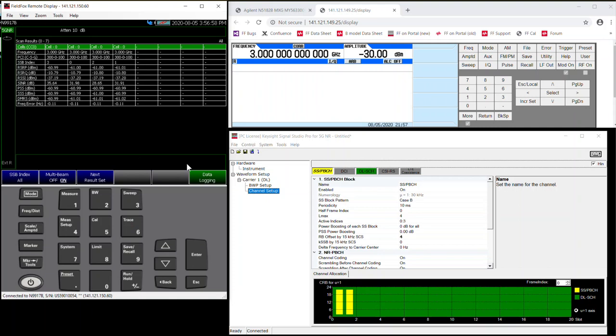Okay. The first thing I wanted to go through is some power level changes because this is an RSRP of minus 61. You had a little bit lower power, so we'll go ahead and drop the power down. Let's do an increment set of 5 dB. And I'll just keep lowering this, and you can see this over here. If you keep looking, it's going to drop. 71, 76, 81. So far, so good. We're dropping the power. Minus 105 RSRP.